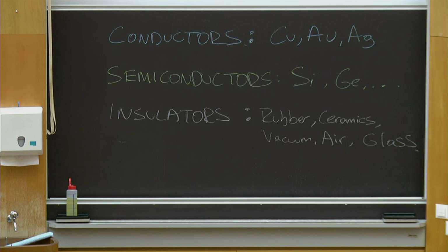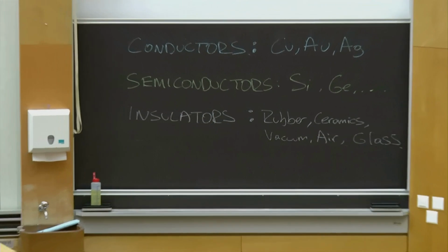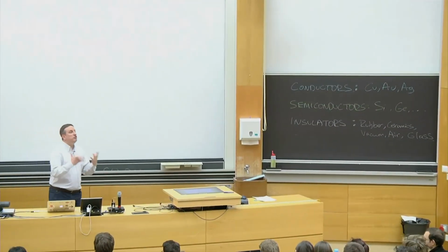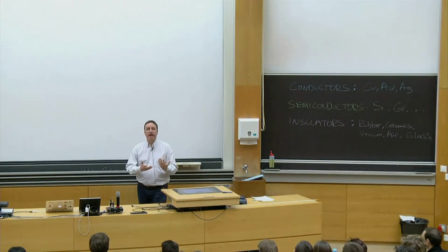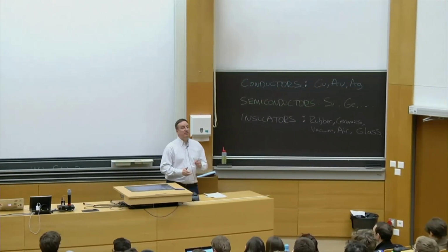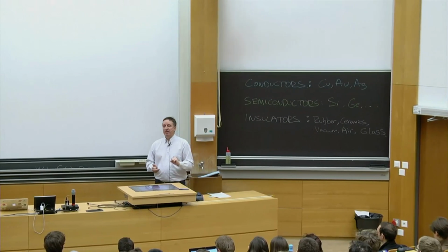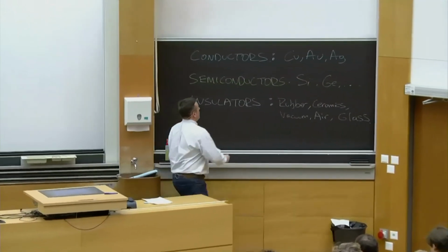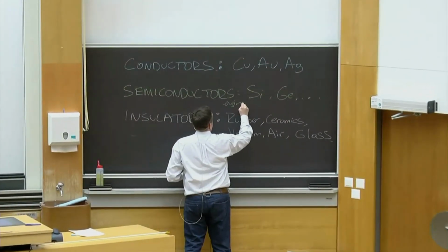And then you can make them dirty. You can add some boron, you can add some phosphorus, and by that you change their electrical properties. You can make them slightly N, negative, or slightly positive, by the amount of impurities that you mix into it. It lets you engineer regions on a small scale that have different electrical properties. This is the great news about it. Silicon on its own is, let's say, less interesting. The interesting part is that you can engineer it. So this is the part that makes life fun.